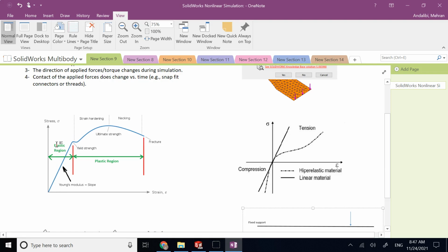One thing I want you to distinguish between is elastic and linear. They are not always necessarily the same. So the material could be linear, or non-linear but still be elastic. Although here both linear and elastic are basically the same thing, because linear means, again, the relation between force and displacement, stress and strain is a line, correct? It's a polynomial of first order.